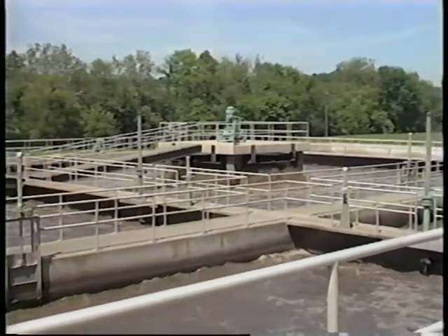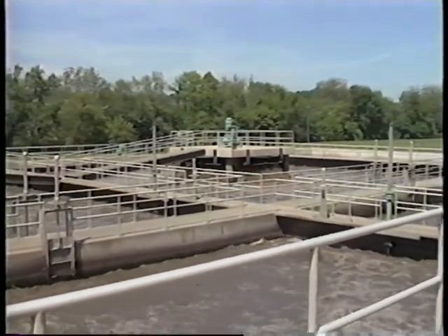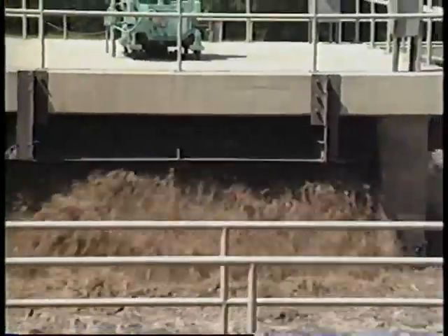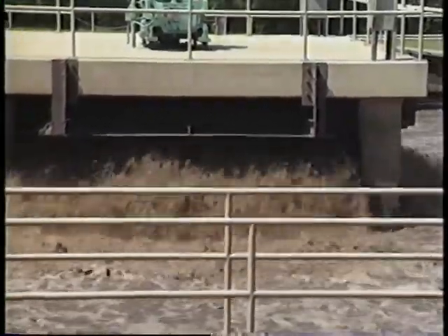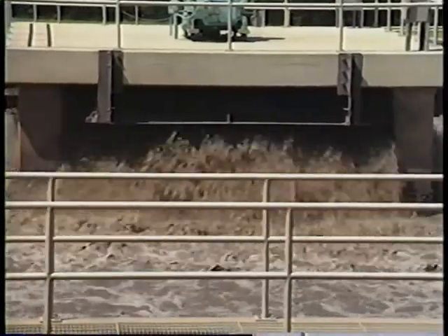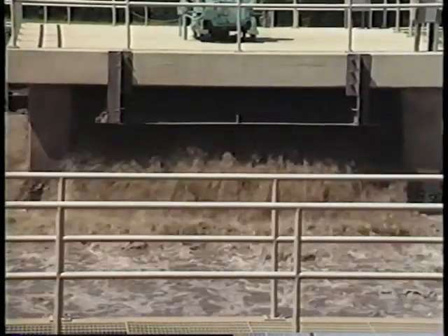contactor. Effluent from the primary clarifier is piped to a large aerator tank, where air is either forced into the wastewater or more naturally induced by mechanical churning of the tank contents. Aerobic bacteria thrive in this environment and feast on the organic material found in the wastewater.